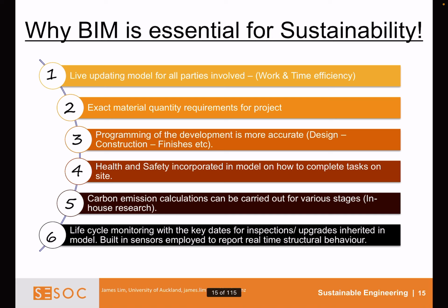We can also carry out automatic carbon emission calculations. The BIM model can be used to compute the carbon emissions from the project during the production and construction phase, and also for the life cycle of the project. This can be used in the feasibility study and gives a good indication on whether a project is in line for the preferred green building or living accreditation.